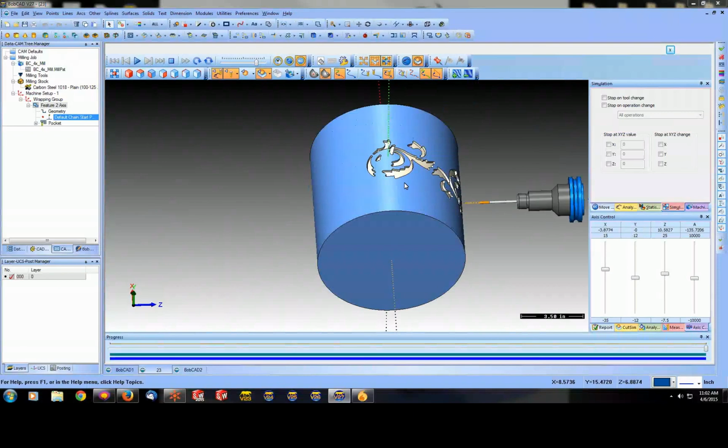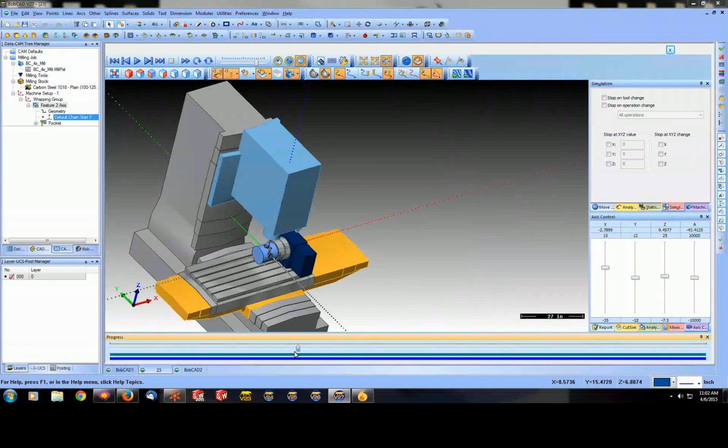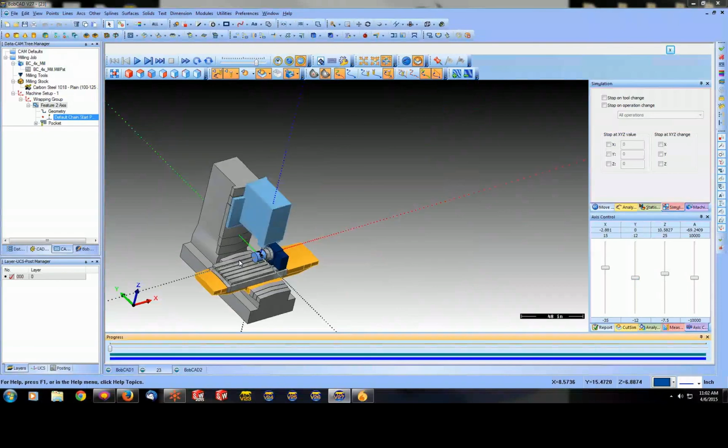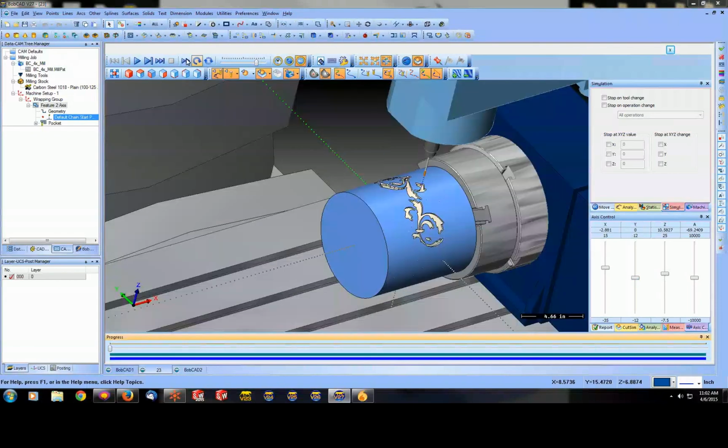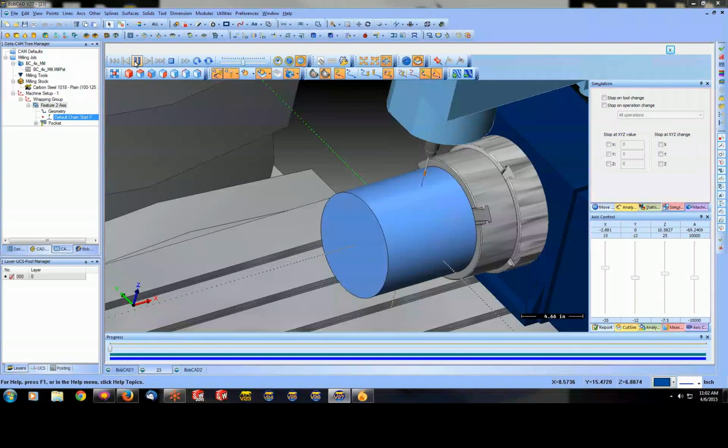And on the rotary, it's going to work back and forth. Rewind that. Here it's doing a pocket, which is much cleaner. The other one is doing 3D cutting, like a contour around the whole thing, where this one's just focusing on that little pocket. It really gives you a nicer finish.